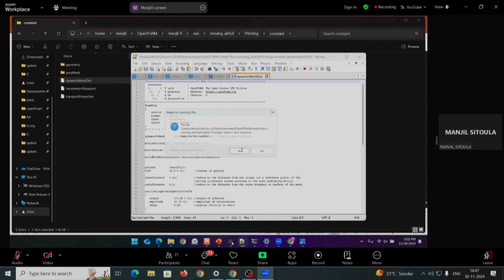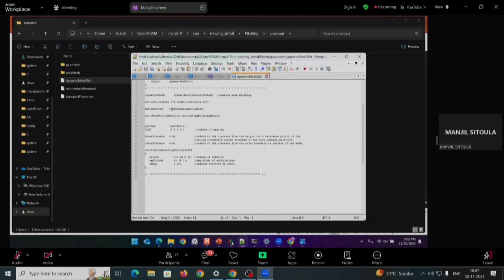Okay, so we can see that we have also used the interpolating solid body solver in this case, but what we need is the origin. This is the additional parameter that is not available in the plunging case, and we have to give the oscillating rotating motion coefficient. When you see the source code of this motion function, we can see that we also need to assign an origin. This origin is computed from the COG, that is the center of gravity point. So we have assigned the center of gravity as 0.500.